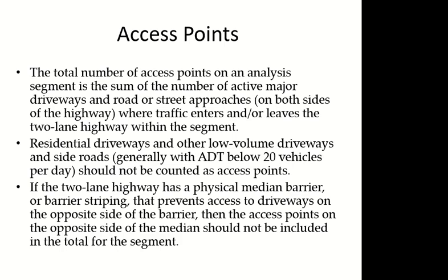I talked about access points. We discussed it for multi-lane highways as well. You have a right in, right out. No crossing, no signal. You can just enter the highway with a right turn, or exit the highway with a right turn. No crossing, and you don't have any signals or roundabout. It's completely free.